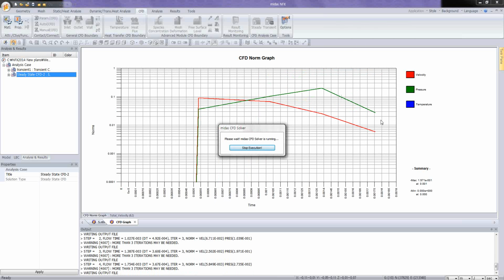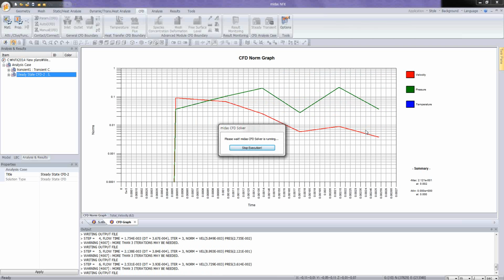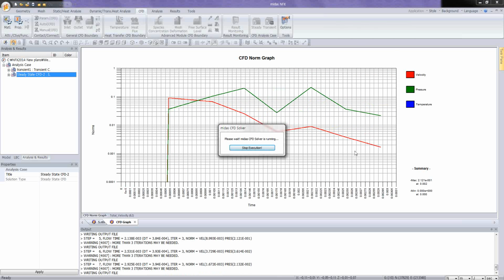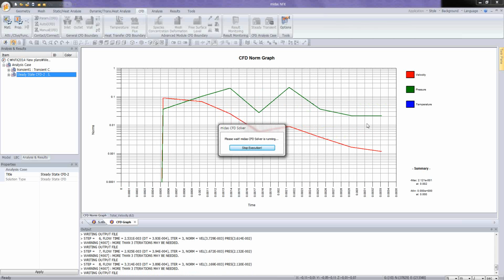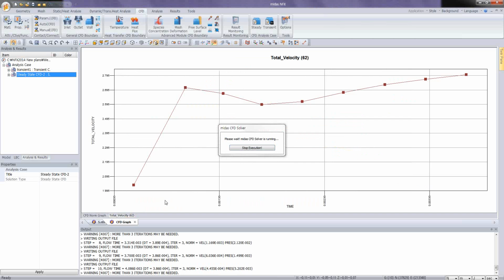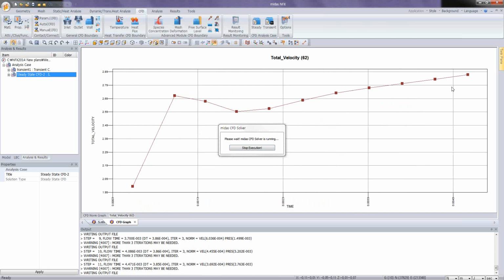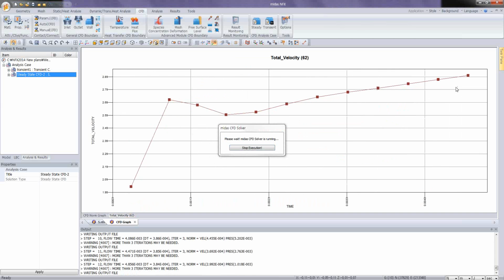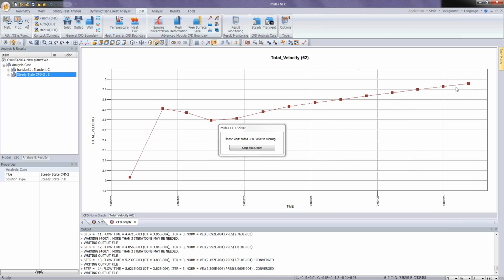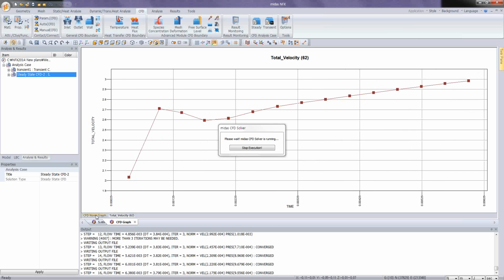So you have the convergence graph. You have two values, the velocity and the pressure, and when they reach a value inferior to 0.001, I have the convergence. So I have to wait a bit until it converges at least. This is the value I am monitoring, the velocity at the outlet. So here I have the value, and I know exactly when I need to stop this steady state analysis: when this velocity reaches a steady state, when it is stable.